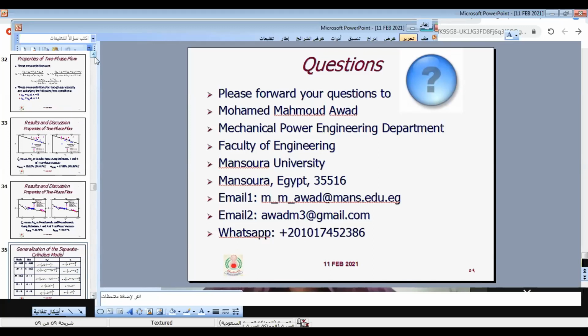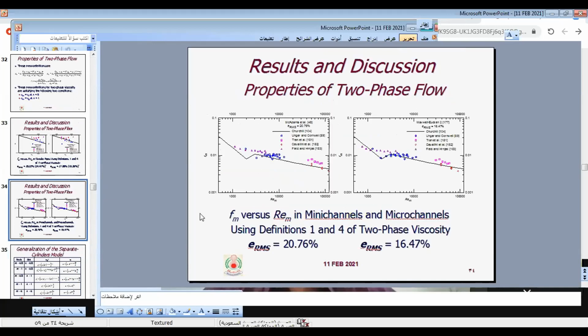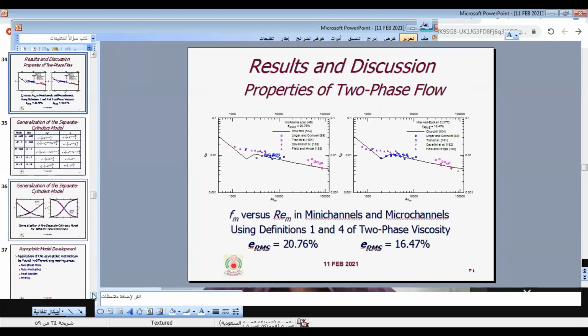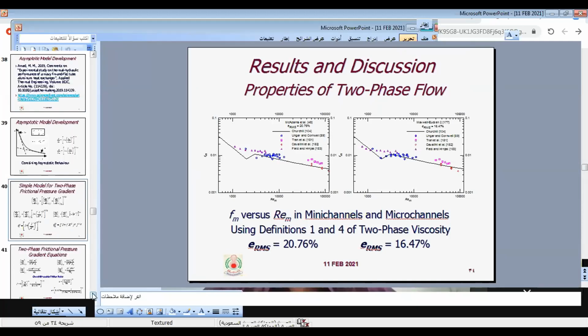From my point of view, the best equation to use for calculating the friction factor is the Churchill model. As shown in this plot, it covers the laminar region, transition region, and the turbulent region. His idea is to express a model chart that was introduced in 1944 in terms of an equation, and his equation also has another advantage when dealing with flow in pipe with roughness. You can take the roughness effect into account also. The equation of his model is shown in this slide.